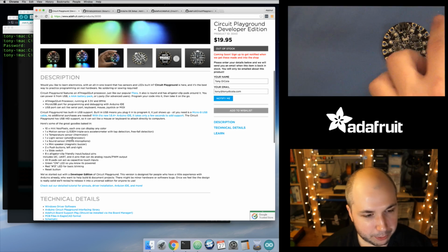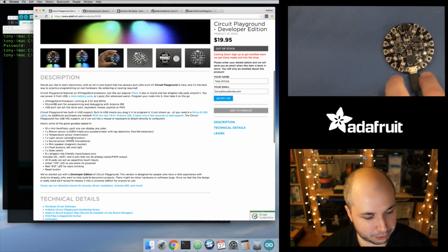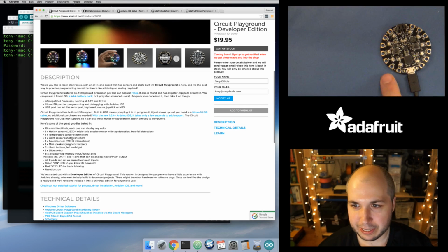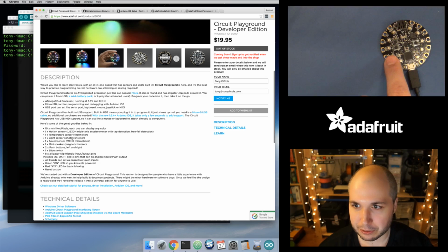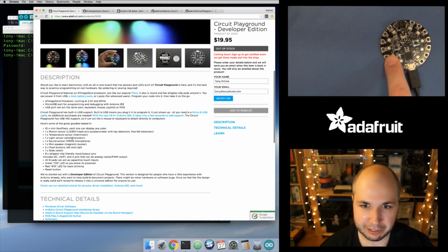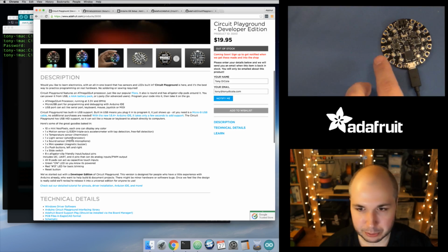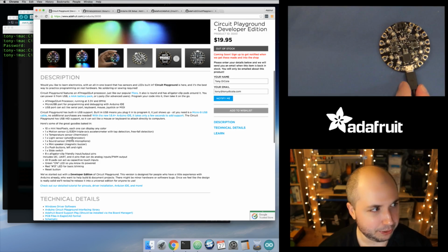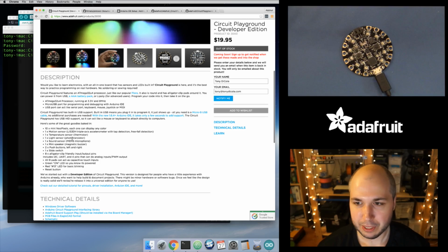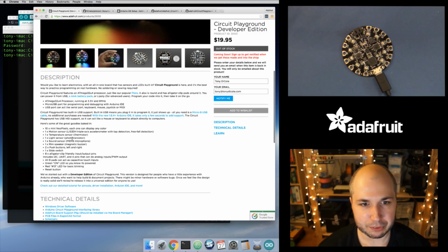And then the other thing I didn't mention, all of those digital inputs and outputs, so there are 8 of them on the sides, those can also act as capacitive touch sensing inputs. And so it's just a real simple way. You use a resistor, and then the capacitance of your finger touching one of these pins will change the time that it takes for a signal to change on one of those pins. So it's a real cheap and easy way to do that kind of sensing. And so we'll go through and do some demos of using all those components.